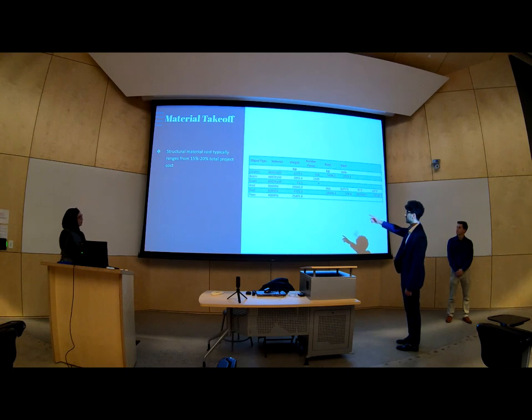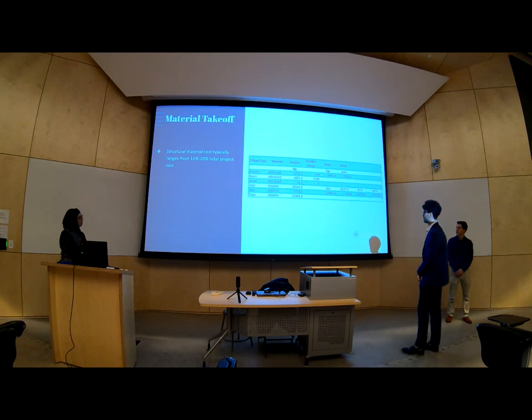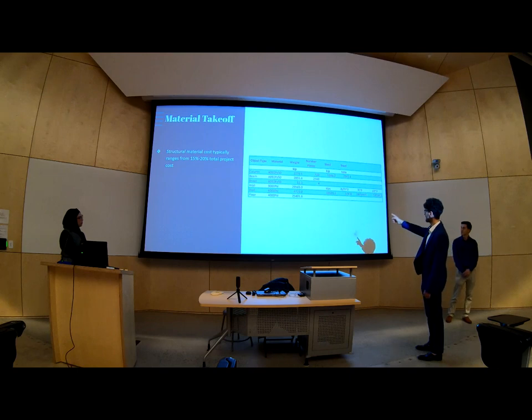And then for concrete, we had walls in 9,000 PSI and 6,000 PSI, as well as the floor in 4,000 PSI, and we added those together once again to get 59,691.6 kips. And if you're wondering what the 150 is, that's just the self-weight of concrete. So in order to convert it to cubic feet, we took 59,691.6, multiplied it by 1,000, and then divided it by 150. So we got the cubic feet. And then we just converted that to cubic yards.